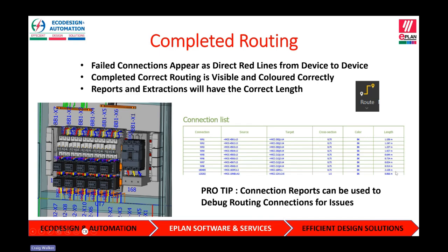This is the whole principle: to get this length and this table, which you can then export to a labeling machine or wire processing machine, which will automatically generate all your wire cuts, lengths, crimped, and labeled, good to go, and then wire straight into the final device.